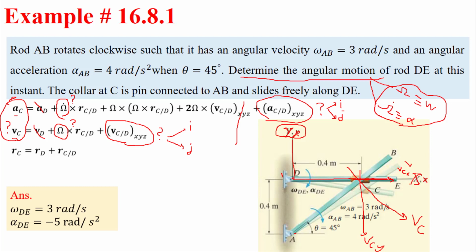And the most important thing is to make those axes follow the link. What do I mean? In this scenario, this is the link the slider slides on. So we'll pick this link and its orientation as well, which will affect the coordinate system. So the x-axis will follow this link and the y-axis is perpendicular to it. Okay.